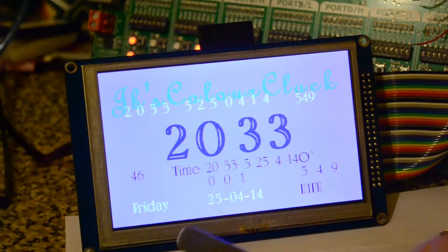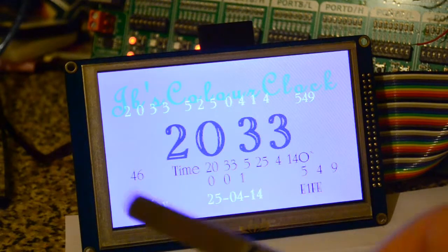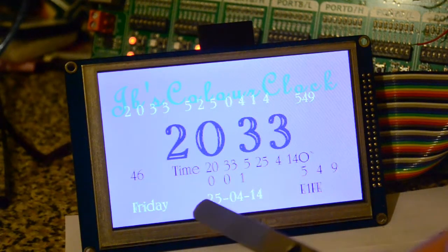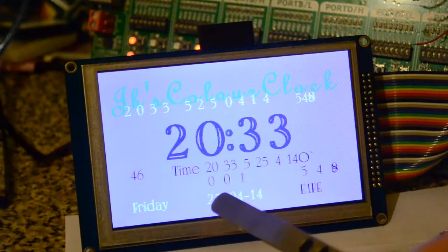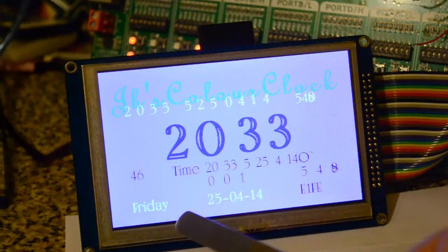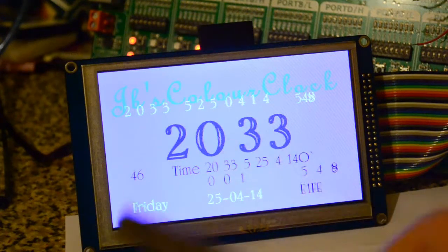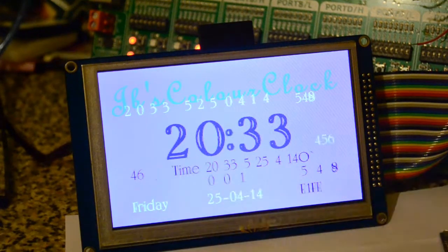I had to use a voltage divider because my PIC microcontroller is only 3.3 volts, and as you know, if you exceed something like 5 volts on a PIC, you'll blow it up. So I'm going to show you how to use a voltage divider, that sort of stuff, and go from there.